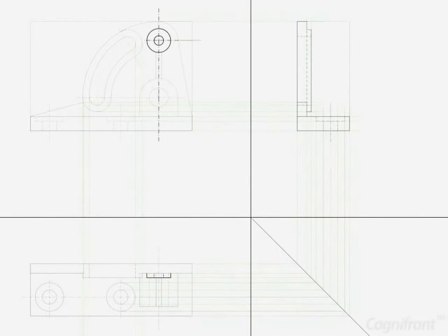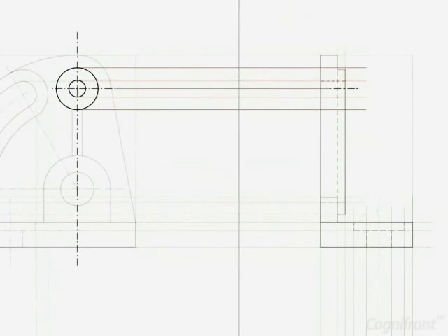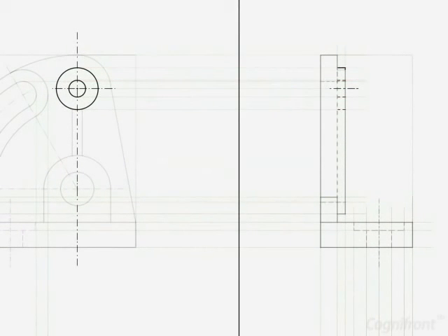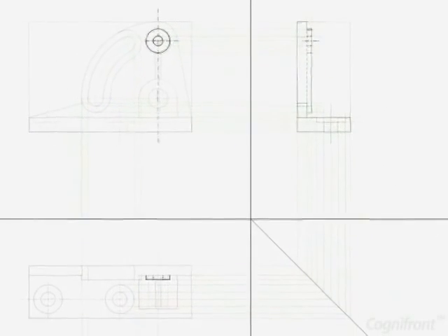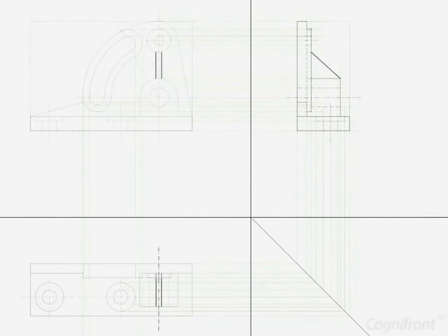Also, take center line of boss hole from front view and generate bossing with its inside hole with hidden lines. Now extend semi-cylindrical extrusion from front view and top view. Don't forget its hole that is throughout the vertical plate. The last remaining part of this object is the connecting rib. Draw inclined line for it.